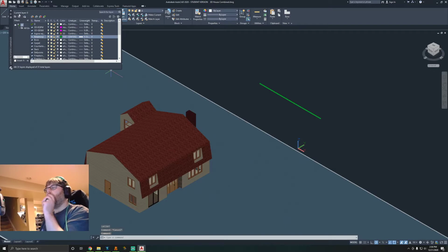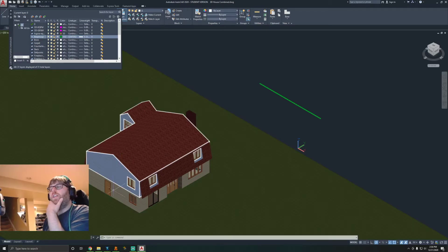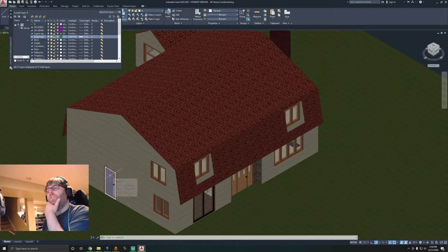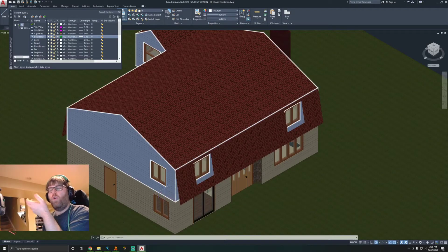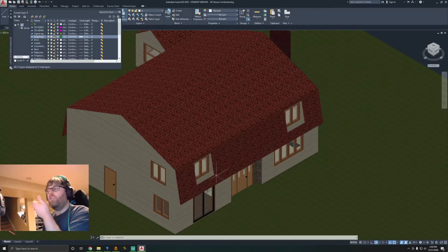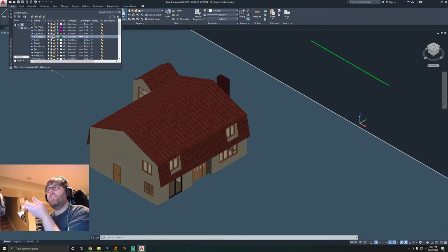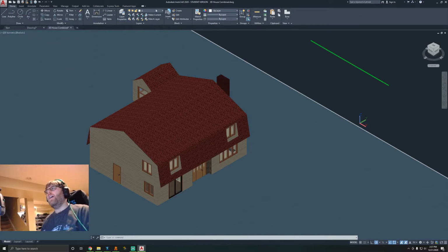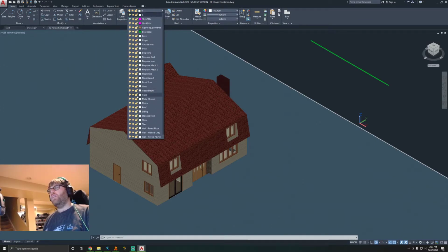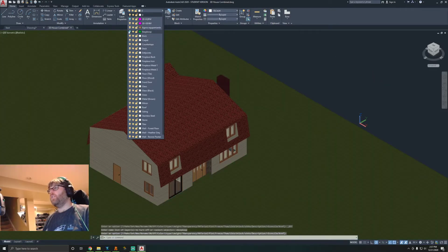But essentially what I would like to get across here is that you could create a whole bunch of different layers, and it helps you organize your drawing, and it allows you to help put different materials for certain things. So if I like a certain wood material, or I want all my doors to be the same, I could call it door or wood or blah, blah, blah. And anything I assign to that, it'll change all the properties of it to that. And you could delete them here, or you could freeze them with these light bulbs and stuff like that, and they'll show up in this list. So if I didn't want to see that beep boop line anymore, I could easily just turn it off and I don't see it. It's still there in my drawing until I turn it back on, but it'll go away.